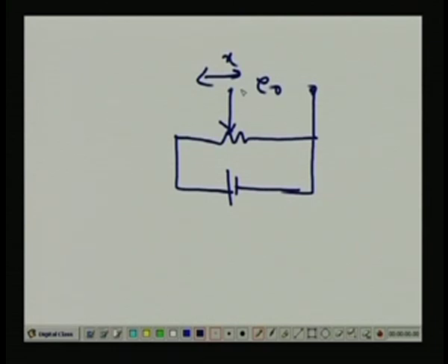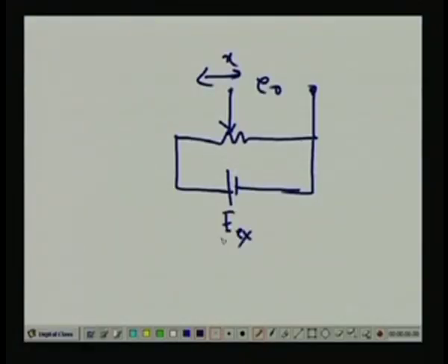Now, you see that the resolution of this potentiometer, that means the output voltage, can be made better and better if I increase the supply voltage value. This is very simple, I just increase the supply voltage, the excitation voltage E x, and the measurement resolution will increase. Whereas, in the case of a passive instrument, it is not very easy.